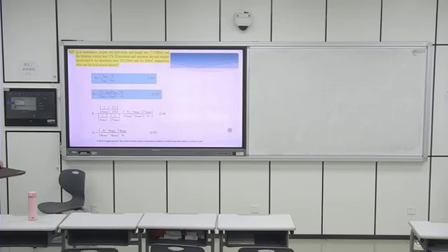In here, it gives you what? It gives you the maximum and minimum dry unit weight. So dry unit weight is what you need to use, right? Of all these equations, only this one uses the dry unit weight. So you need to choose this equation, not this, not this.